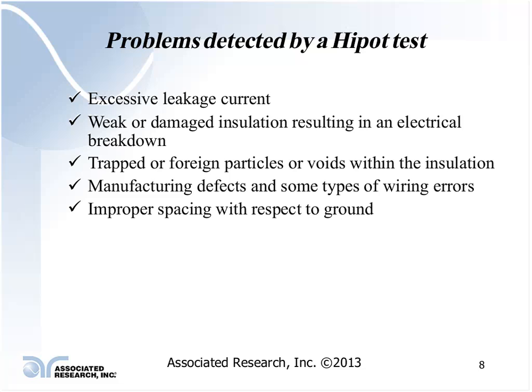But what happens if that ground circuit is faulty? Then that leakage current could end up flowing through the individual. If you're not running from any type of GFI outlet or protected outlet, that leakage current could create a significant shock hazard to the user. That shock hazard could, at a minimum, create a startle reaction.